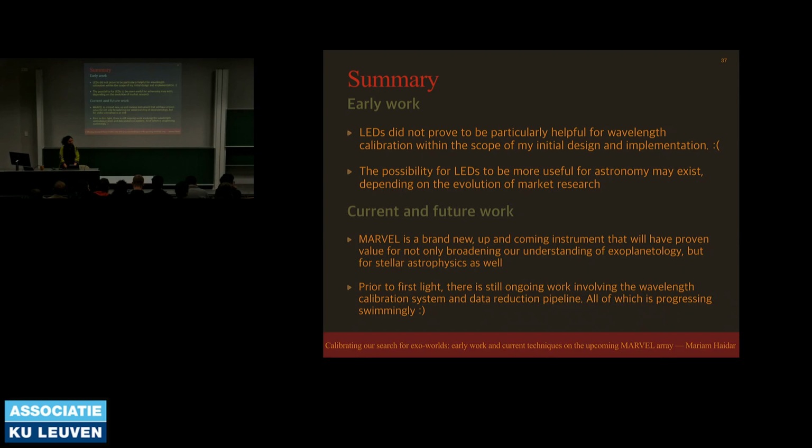So that's actually why I wanted to ask whether you considered another way to couple several sources into a single fiber, using an approach of separating, like having several pupils or subpupils inside your focuser or injecting lens, instead of trying to de-disperse the light. So a more parallel design, where instead of using a grating you have micro lenses in front of each LED, and then a larger lens to inject.